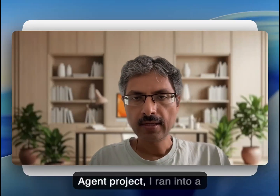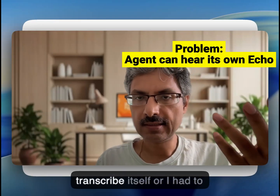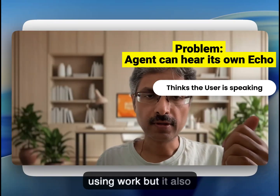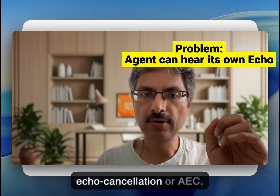In my voice agent project, I ran into a slightly annoying problem. The agent could hear its own voice through the speakers. That meant it could accidentally transcribe itself, or I had to mute the microphone whenever it spoke. So muting worked, but it also meant I couldn't interrupt the agent. Conversation felt less natural, and so I needed to add Acoustic Echo Cancellation, or AEC.